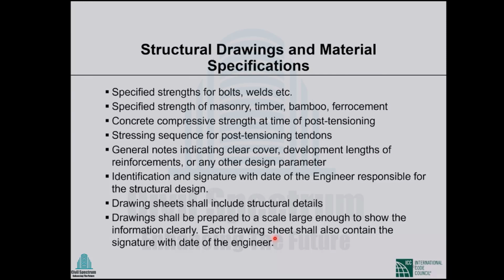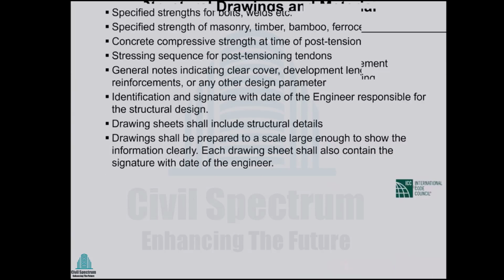Concrete compressive strength at time of post-tensioning. Stressing sequence for post-tensioning tendons. General notes indicating clear cover, development lengths of reinforcement, or any other design parameter. Identification and signature with date of the engineer responsible for the structural design. And then drawing sheets shall include structural details. Drawings shall be prepared to a scale large enough to show the information clearly. Each drawing sheet shall also contain the signature with date of the engineer. So this is quite detailed, all the information. So we should follow these guidelines.